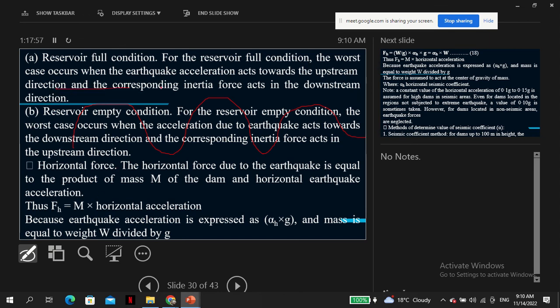The net effect is that these forces are acting horizontally. There is some horizontal acceleration, alpha h, and also a vertical acceleration, alpha v. The worst is the horizontal acceleration, because that one causes shear forces on the structure, the soil and our buildings as well.